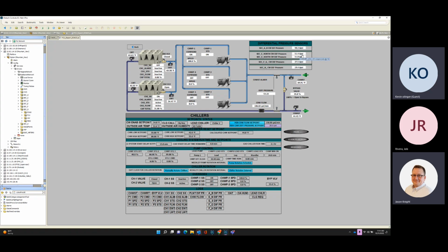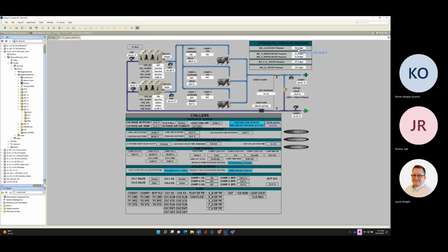Okay, so on the upper right, you can see the different loop pressure sensors for the chill water system. Sector AB chill water differential pressure right now is running 50.3 pounds. So we have a bunch of questions going back to engineering saying, hey, we're running 50 pounds in all these sectors. And it's the result of having to run sector H at a minimum of 20 pounds right now. So you can see that 20-pound PSI differential pressure set point is the minimum we're controlling to.